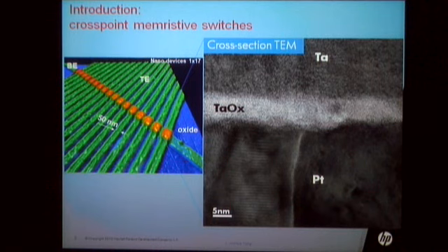The oxide material itself is a wide bandgap semiconductor. Inside the oxide, there are a lot of oxygen atoms missing, leaving a lot of oxygen vacancies. Oxygen vacancies can serve as an unintentional dopant to dope the oxide semiconductor material. And different from dopants in silicon, such as boron, here the oxygen vacancy dopant can actually be moved by electric field.